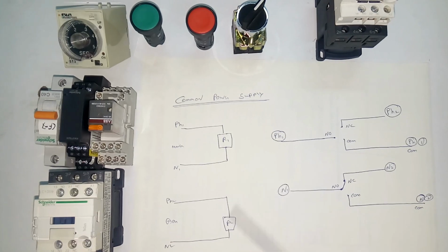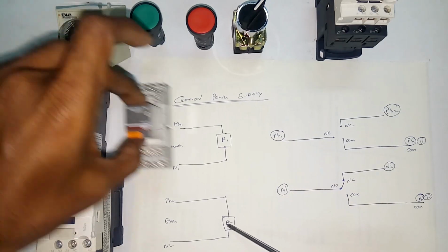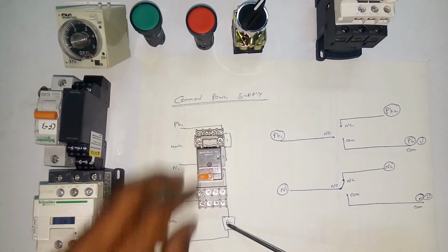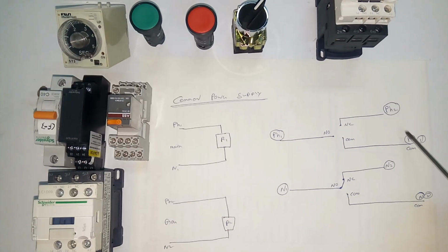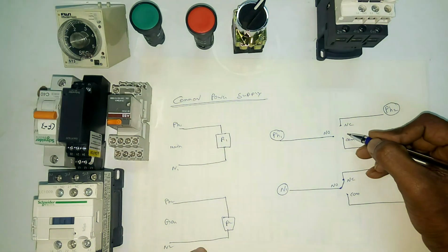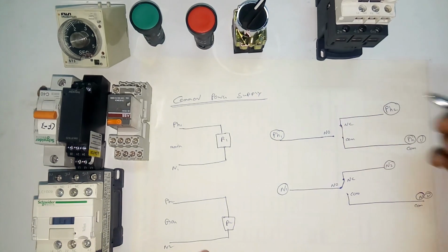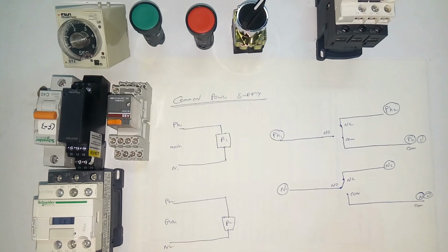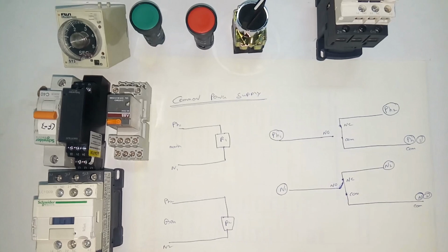The main power supply, that means the ordinary power, is not a problem, but the control power should not be switched off, because the control power controls everything in the ATS panel. So here we need to make a common power supply for the ATS panel, and that's why I am arranging this diagram. If you have any external battery or other external source for continuous supply, there is no need to arrange this common power supply. But if you don't have an external uninterrupted power supply for the control, you need to arrange this one.